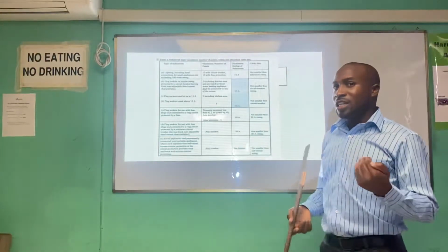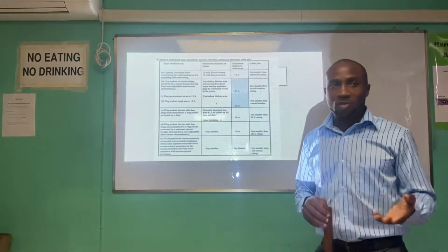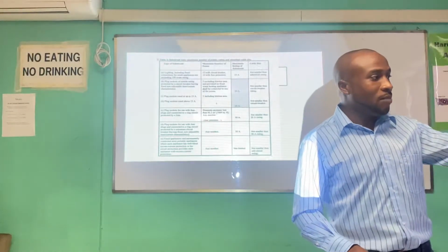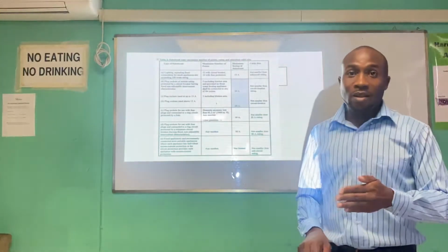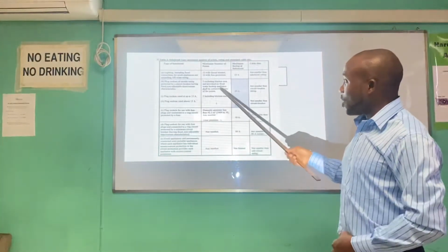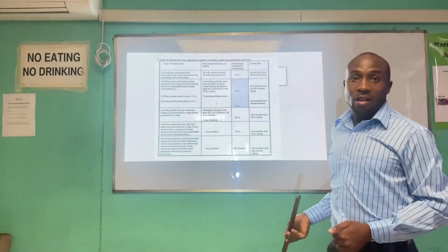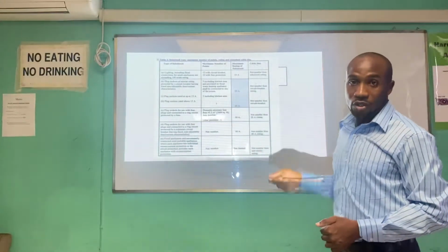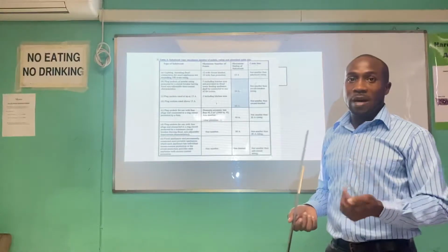Because in your design, you're going to say, okay, it's a 2-bedroom house, and you're going to tell the designer that you need plugs on this wall and this wall and that wall. So whenever you decide how many plugs you're going to need in all, it will tell you exactly how many circuits for plugs you will need, and you'd have to design your panel accordingly.